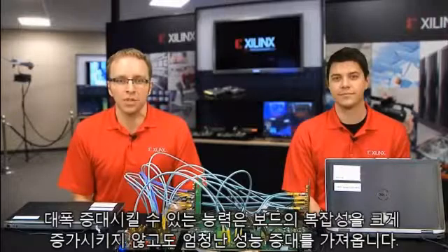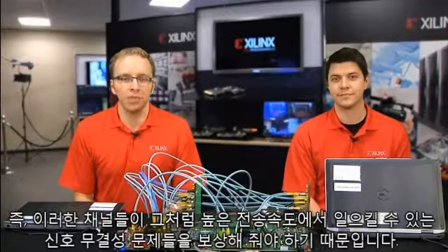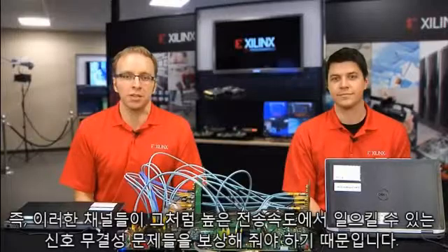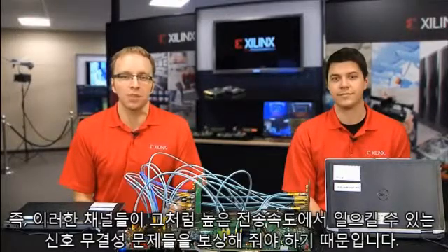We've all seen our customers clamoring for 10 gigabit performance over anything from a simple chip-to-chip connection to a difficult multi-connector backplane. The reasoning is clear. The ability to drastically increase bandwidth over the smallest number of pins results in massive performance gains without a drastic increase in board complexity. Of course, this does put a lot of stress on the transceivers, leaving them to compensate for the signal integrity problems these channels can create at such high line rates.